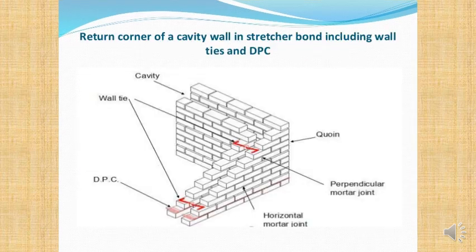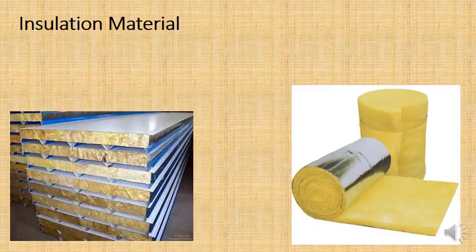So how would you go about building a cavity wall with masonry blocks? Well, basically you would build two walls right next to one another, and you would probably have little ties which are called wall ties, and they basically stop the walls from leaning into one another, and so you've got an even gap all the way through. Now, there's a few advantages I've already talked about, the main one being insulation.